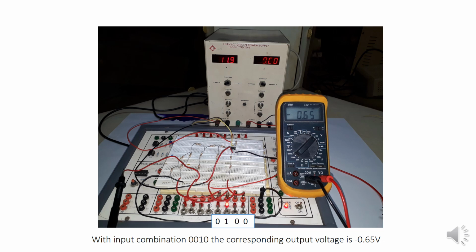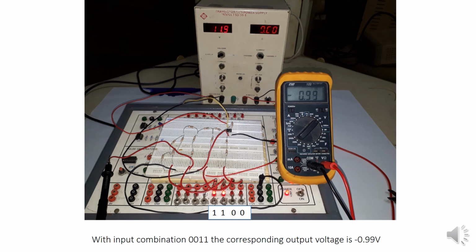For the next value, I am making the digital sequence 0, 0, 1, 1, which is binary equivalent of decimal 3. Hence the voltage is multiplied by 3. Nearly we are getting 3 times the LSB value. Likewise, we can verify the output for all input combinations, starting from 0, 0, 0, 0 to 1, 1, 1, 1 by toggling these binary input switches. Okay, clear?